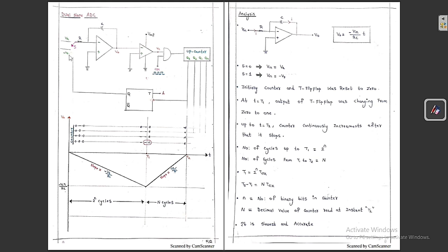This value we know. Now after some time, whenever a negative triggering occurs, we are going to switch to the VA voltage, the analog input voltage that we don't know. We have to connect the switch and then we are going to figure out this value. So listen carefully to how we are going to get this. See, this is basically an integrator circuit.